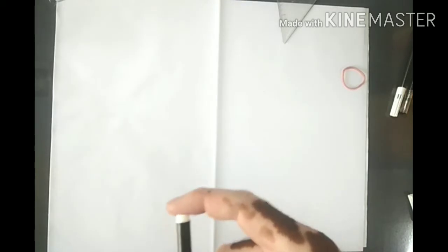Yes, next problem. A vertical square prism, base 50 mm side of base and 100 mm long, having its faces equally inclined to VP, is completely penetrated by a horizontal cylinder of 40 mm diameter and 100 mm long, the axis of which is parallel to VP and 6 mm away from that of axis of prism. Draw the projection of the solid showing the curves of intersection.